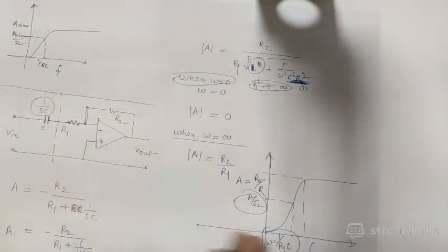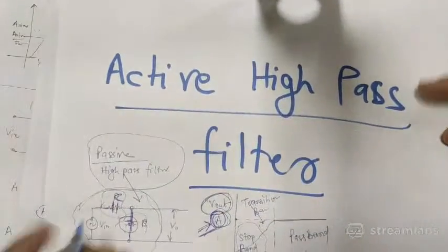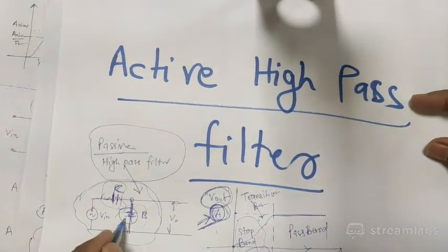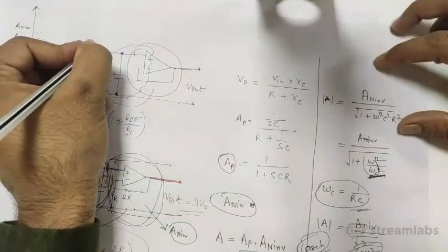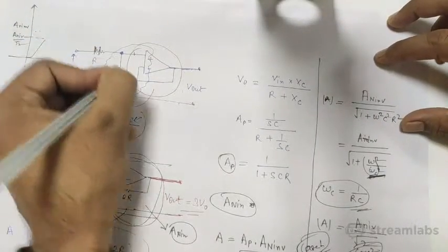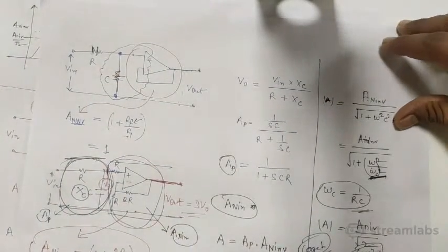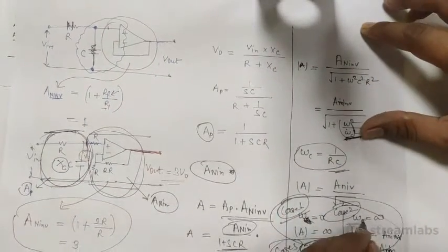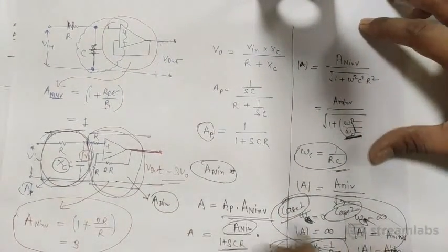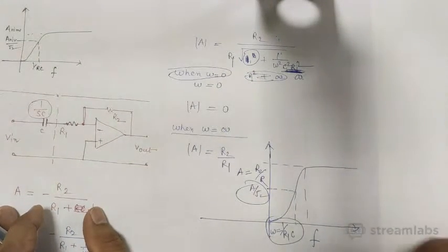Okay, so we have done a mistake in the previous circuit. You just correct this. There should be capacitance here and resistance here. Also there will be capacitance here and resistance here. Make corrections. Then if you do suitable analysis, here also you should put omega equal to 0 instead of omega equal to infinite, then you will get the correct result. So change our analysis according to that. Okay.